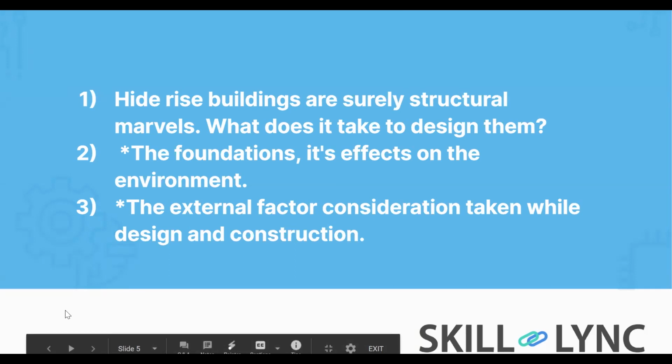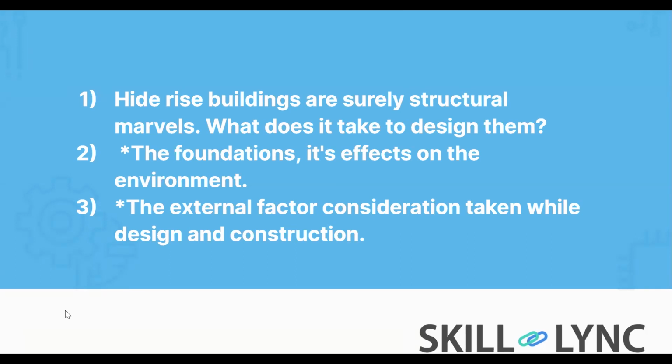So generally, the foundation will be pile foundation for all the tall buildings. In some cases, you can also go for a raft foundation, but this will be where you find proper rock material at a very high level in the ground. So it depends on the soil condition, but in most cases it will be piled foundation for tall buildings.